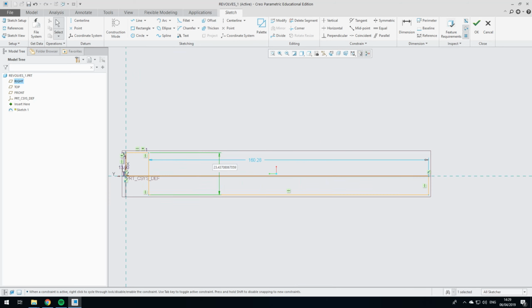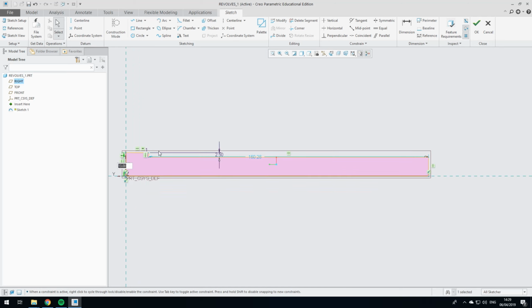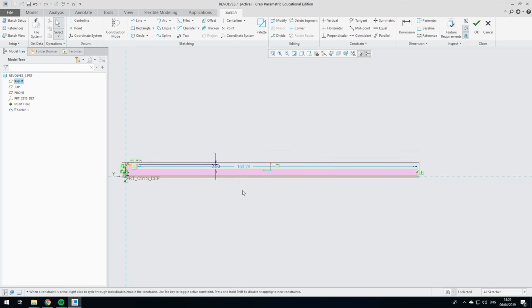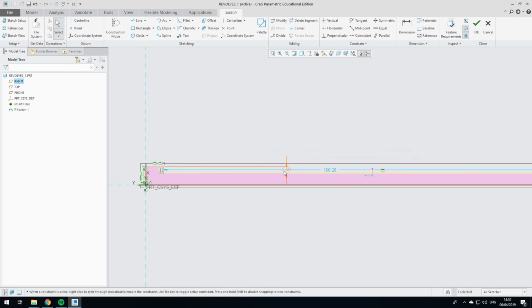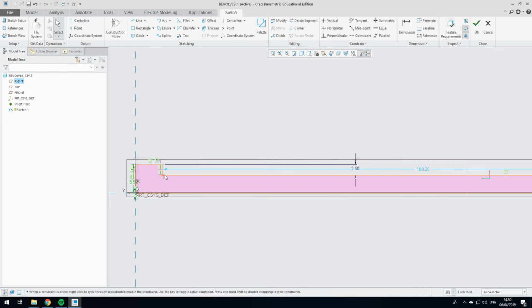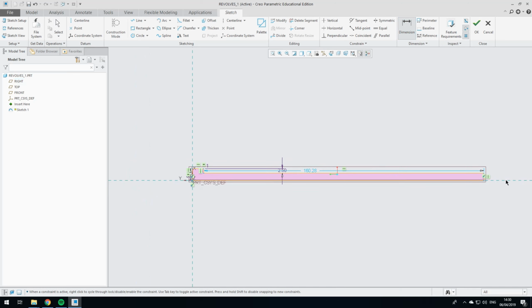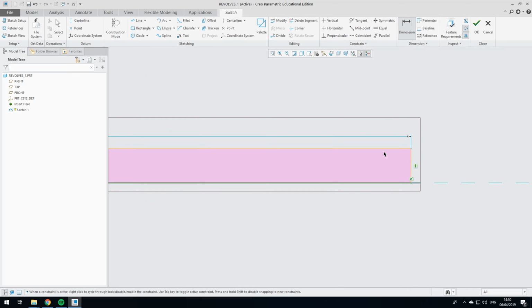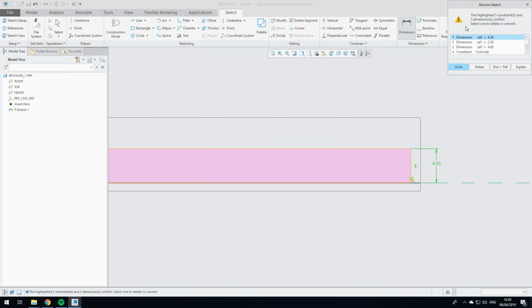The outer face of the top of the cap head I know is 13, so that would be half of that, which would be 6.5. And we know that to get an M8 we're going to need 4 mil in this axis here, so we've added minus 2.5. Equally, if you're less comfortable doing the maths, or if you want to do it for definite, you can click dimension, hit the two faces that you want to measure between with your left mouse button, hit the middle mouse button, and it will set you up there as 4.